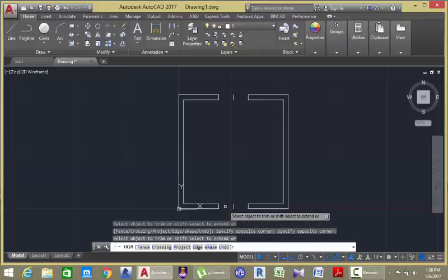The option is yours. Also, I need to erase this line, but instead of going to the status bar and selecting the erase command, or selecting the line and deleting, the trim command gives me an option, which is the erase option. If you look at the command line, you have an option which is erase. The second letter, the R, is in capital letters, also in a blue color. So I'm not going to use the first letter in this case. The reason why AutoCAD does that